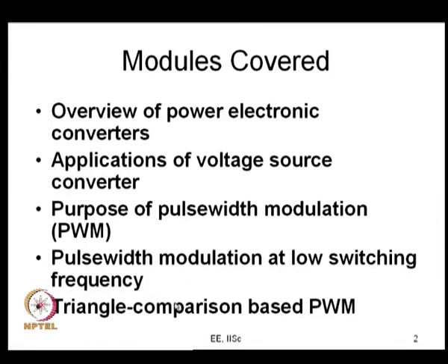That happens in high speed drives, and in such cases the ratio of switching frequency to fundamental frequency is low, and once again this becomes relevant. And what I would say is, rather than its relevance to the present context, this has more value to us from a learning point of view. It is a very useful step to go through this, to learn how to control fundamental voltage and how to handle the harmonics, which are the two purposes or objectives of pulse width modulation.